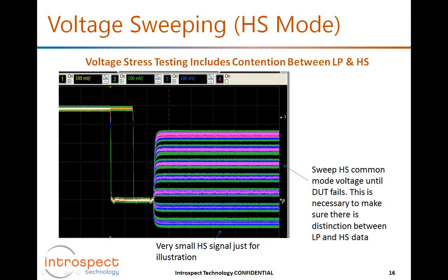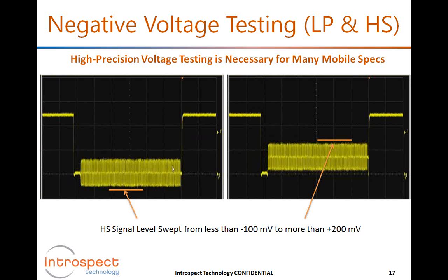Very similar concept, and perhaps just a slight elaboration on it, is that, again, because of the mobile nature of the terminals and the very low-cost nature of the power regulators and the power supplies and the PCB material and the decoupling capacitors, it is actually quite possible that signals can go negative in voltage, and the receiver is supposed to tolerate this.